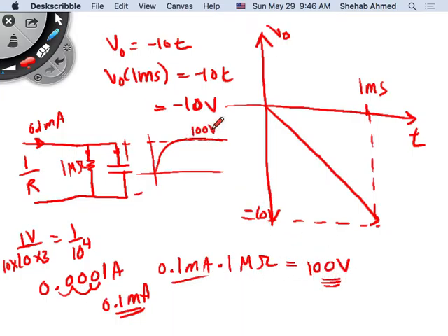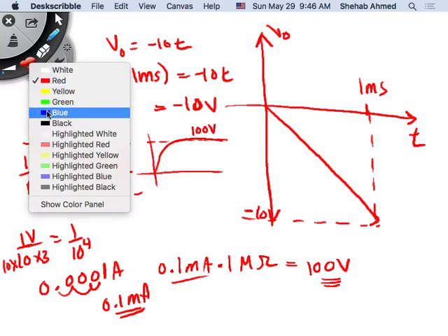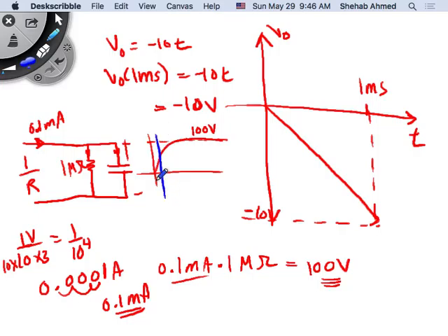When does it reach 100 volts? From 214, at a long period of time. Periods of time related to RC circuits we quantify using time constants, right? After one time constant, the voltage is so and so. After two time constants, so and so. After six or seven time constants, the voltage reaches steady state, right? So after many time constants, the voltage will reach 100 volts.